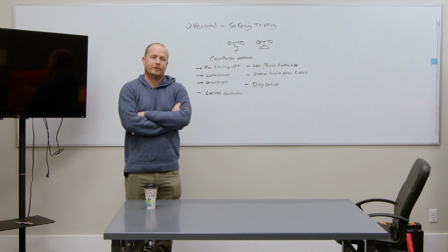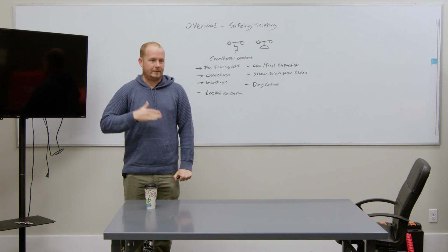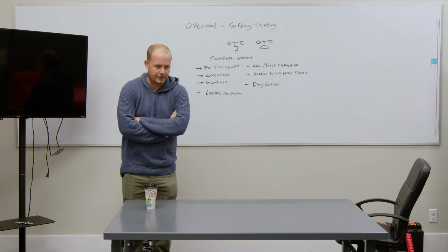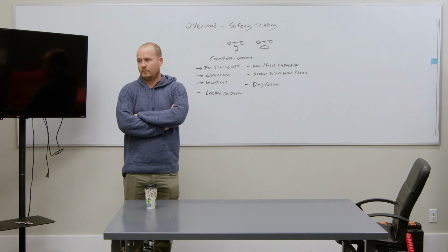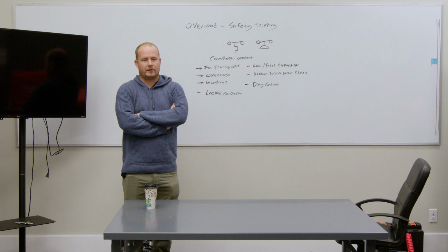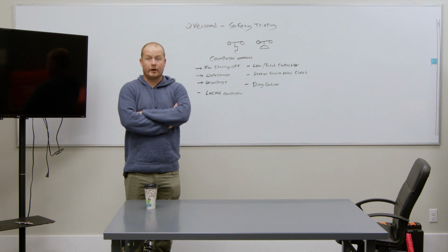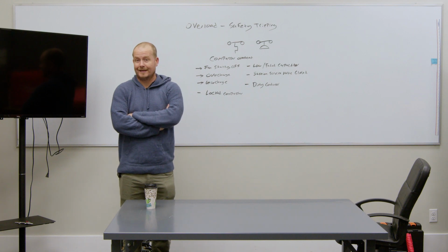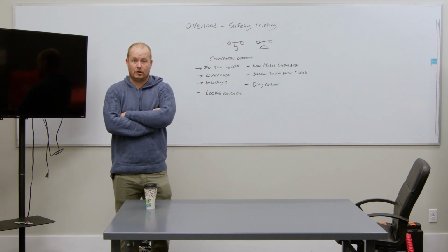But why is it able to do it so quickly? Why can it reset so quick? Because normally, if you have a compressor that's overheated because of like being low on charge or something, you got to run a hose on it in order to get the thing to reset, or let it sit for hours and hours and hours. But why, in the case of a failed capacitor, does it reset so quickly? It's not as hot inside. What? It's not as hot inside. It's more hot. It's hotter, but the heat is isolated in the windings where the thermal overload is. So it's actually higher temperature, but it's right where that thermal overload is.